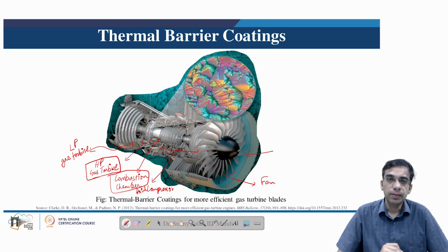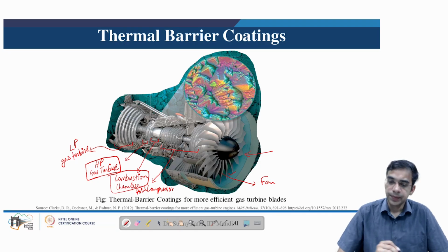So specifically speaking, the thermal barrier coating is applied on the surface of the gas turbine blade to minimize heat flow in the gas turbine blade, because if heat flow will take place, there will be the issues of creep and fatigue types of failure which we want to avoid at all cost, because in gas turbines, as we have understood from the previous lessons, the gas turbines are rotating at very high speed, and presence of this heat deteriorates the performance of the gas turbine blades.